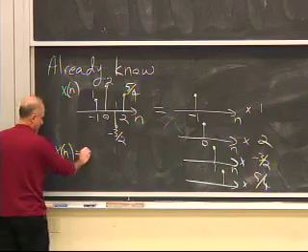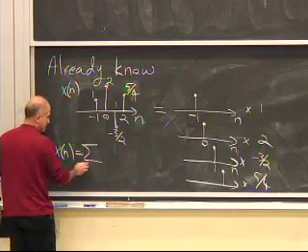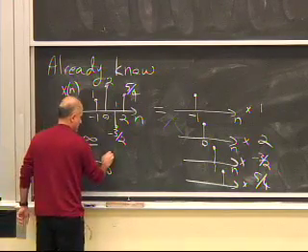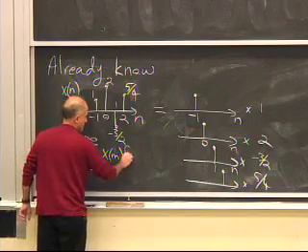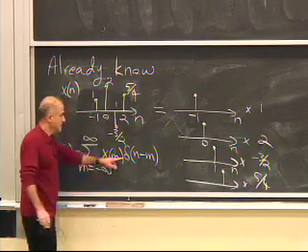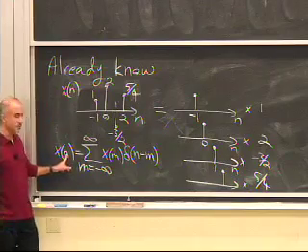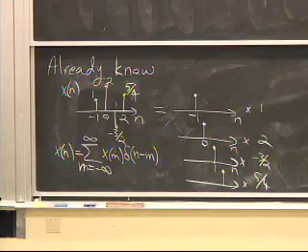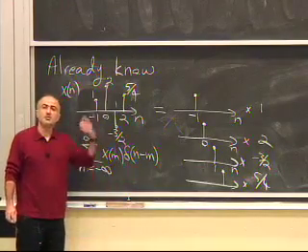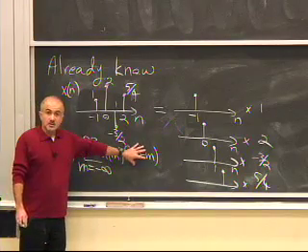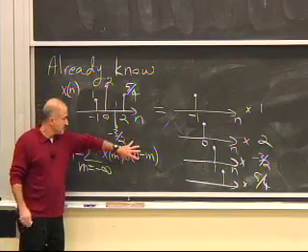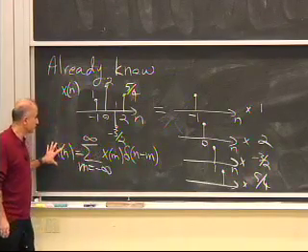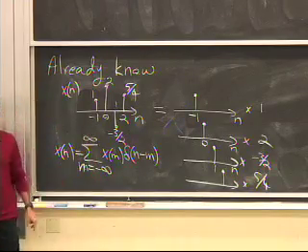And we did this using the closed form, sum from minus infinity to infinity of x sub m, delta of n minus m. So the signal x at any sample is a linear combination of shifted impulses. We've already done that. And the reason we decompose the signal in this way is that we deal with LTI systems. And for LTI systems, all we need is to characterize what the response is to one of these impulses. And from that, we can infer the input-output relationship for any arbitrary input.